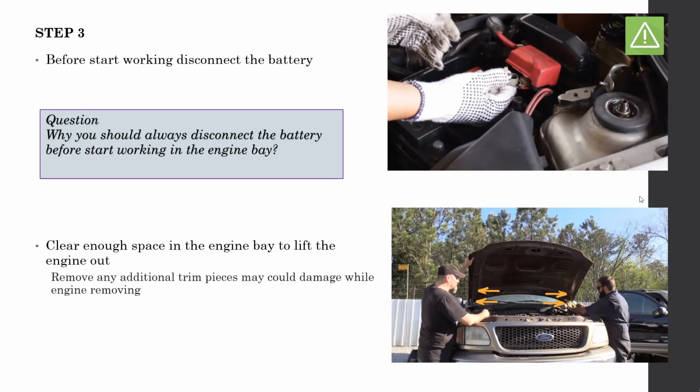For some reason, if we drop a small tool in the wrong location by mistake, that could end up cranking the engine. To avoid that, before we work in the engine bay, at all times we should disconnect the battery. That's the correct practice, but most of the time most people are not doing that.